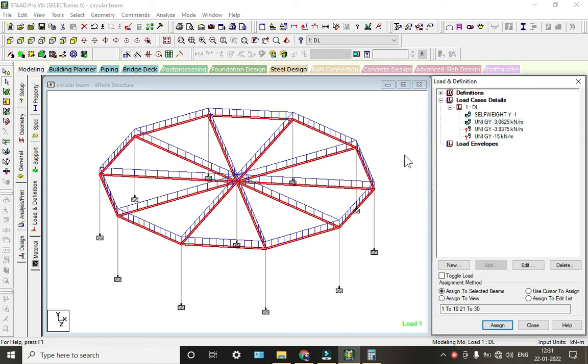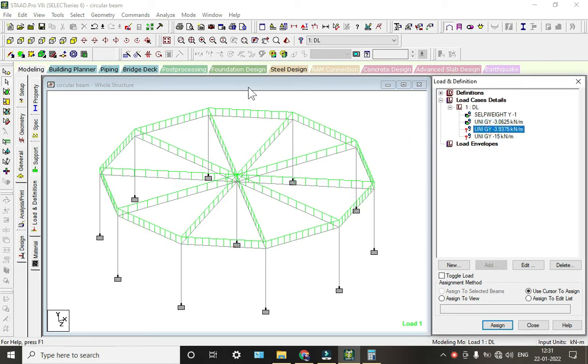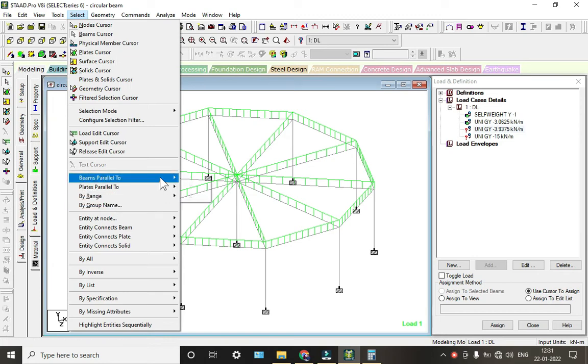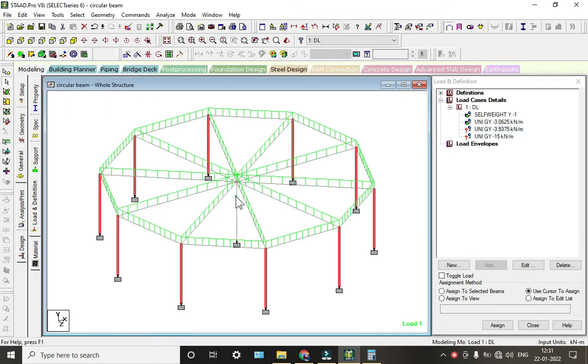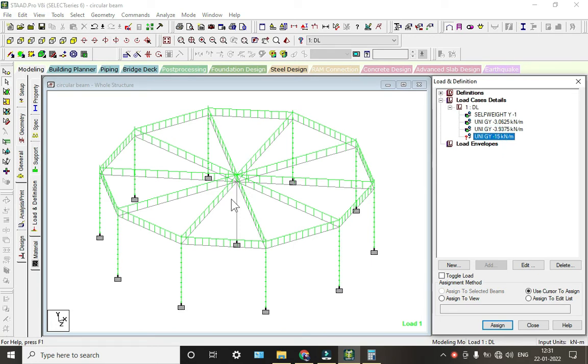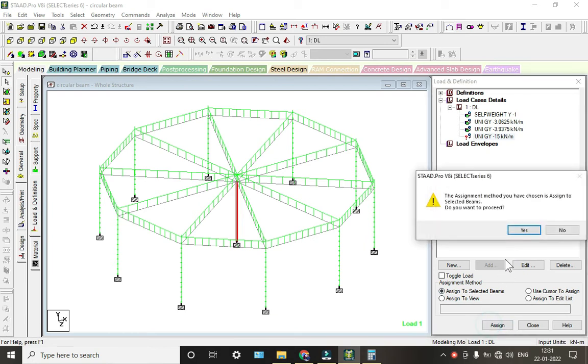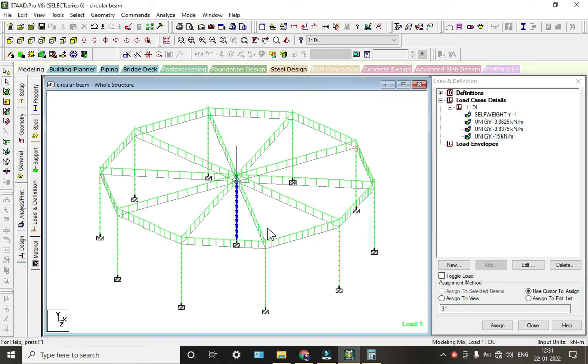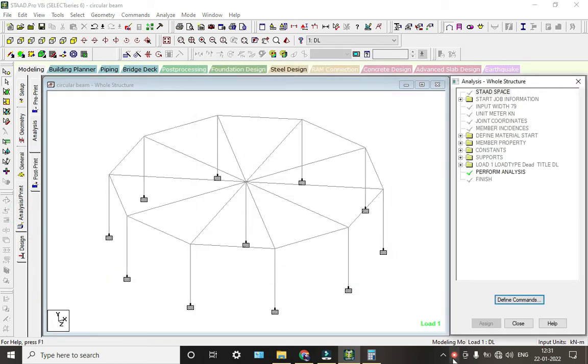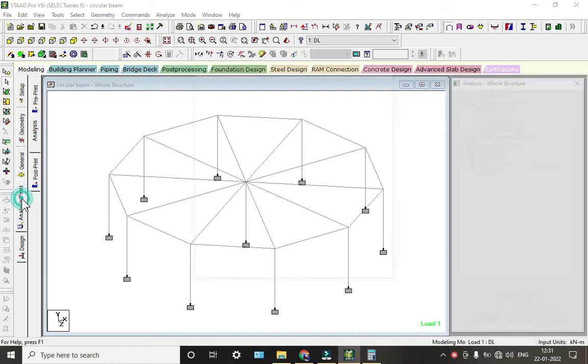Define parameters. Here I am going to take FC as 25 and Fy as 415. Fy main, so maximum reinforcement is 20, I will take 25, and the maximum sectional is 16. Click on add and close. Now go to commands, click on design beam, add, design column, add. We don't have any element, so we'll take off, add and close.